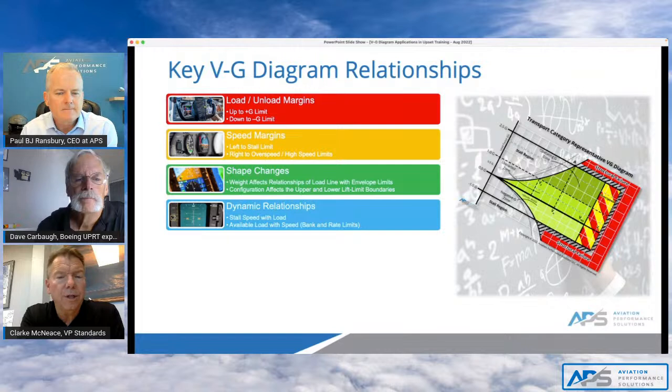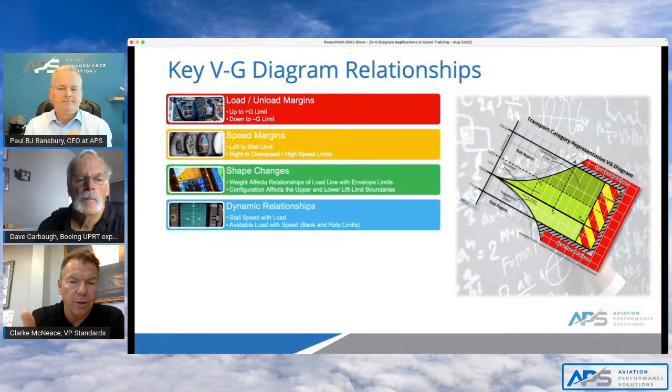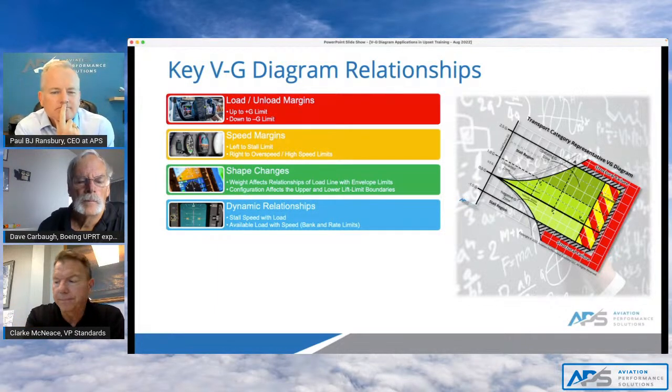No, I think it's good. Just again, I'll probably reiterate that from an aerodynamic standpoint, all of us pilots understand that a heavy airplane has higher stall speeds than when we're lightweight. And basically that is the same aerodynamically from a load standpoint, pulling G's. Same thing, when you increase G load, AOA goes up, drag goes up, stall speed goes up.